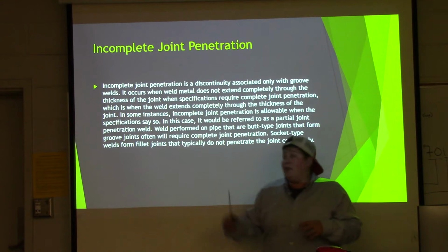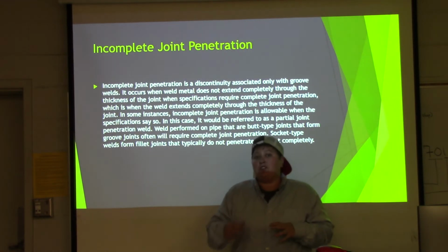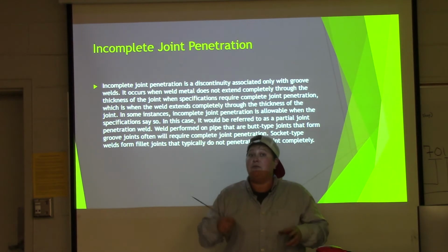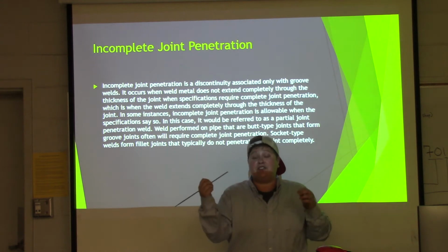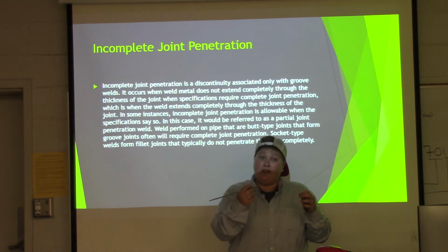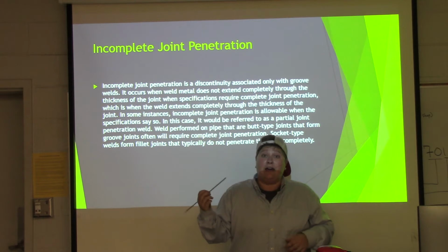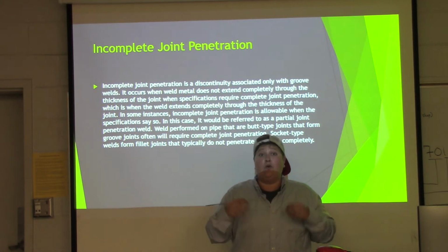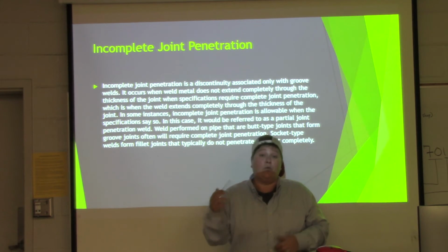With that being said, on that previous slide, you're not going to have to worry so much whenever you are TIG welding, but you will still get that silicon if you're not actually pushing it far enough ahead of you. So with that, you will still have to clean out that silicon, or you will get entrapments whenever you're going over your hot pass, or with your hot pass.